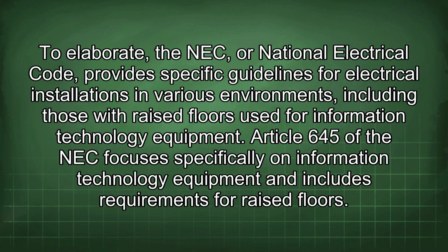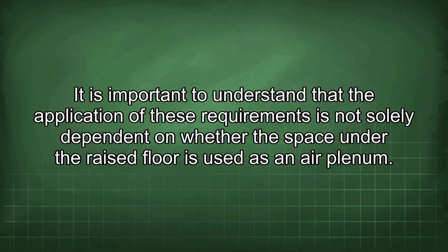To elaborate, the NEC, or National Electrical Code, provides specific guidelines for electrical installations in various environments, including those with raised floors used for information technology equipment. Article 645 of the NEC focuses specifically on information technology equipment and includes requirements for raised floors. It is important to understand that the application of these requirements is not solely dependent on whether the space under the raised floor is used as an air plenum.